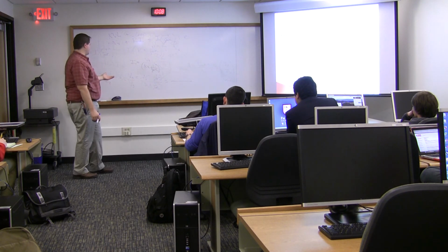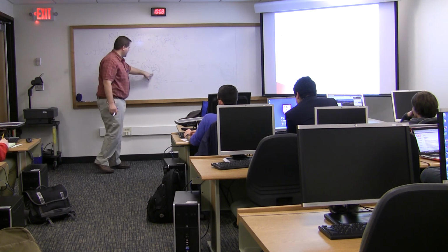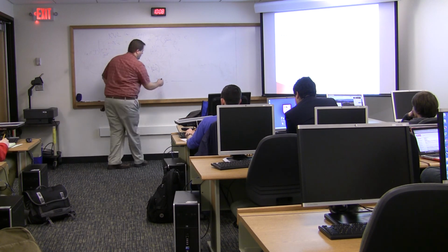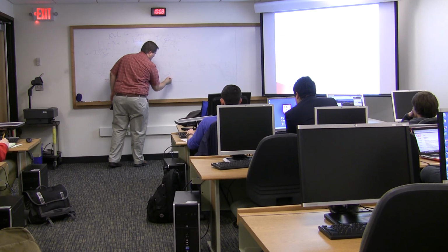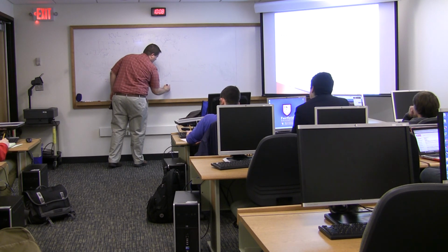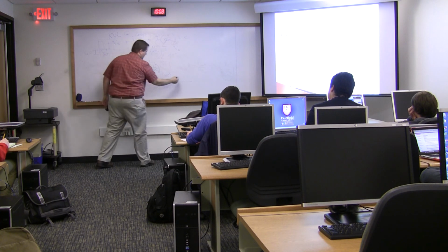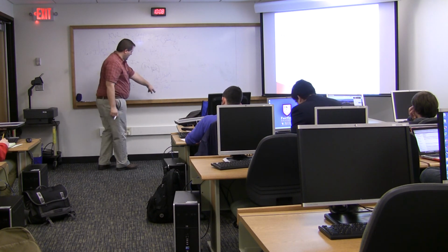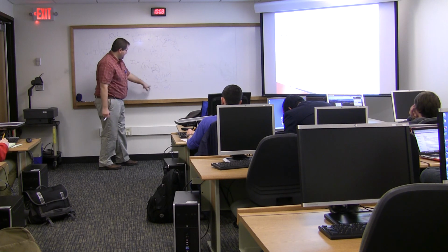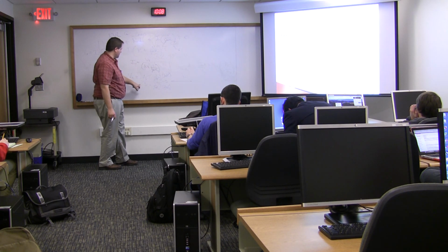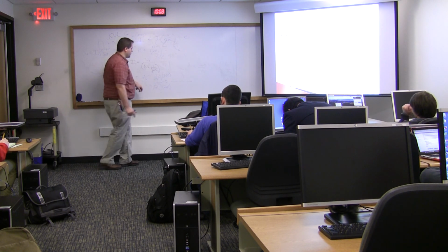So in this case, if I were to clean it up, I would multiply top and bottom by j omega C. So the j omega C here, on the top and the bottom, would cancel this one. I'd be left with a 1. And on the bottom, it's going to distribute in. It's going to give me a 1 here, and a j omega RC.